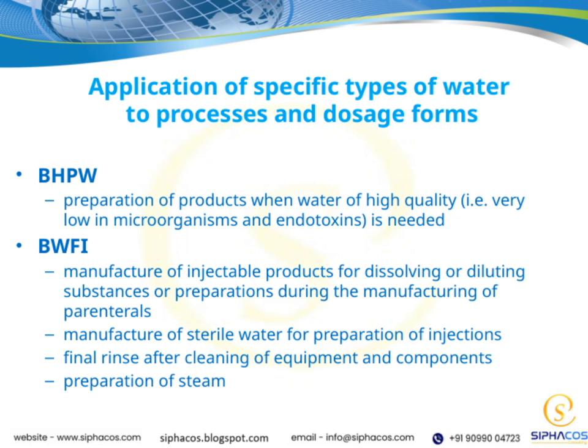Next, we have BWFI, or bacteriostatic water for injection. This is used mainly in the manufacture of injectable products, especially when dissolving or diluting substances during the production of parenterals. Because these injections go directly into the bloodstream, the water must be sterile and free of harmful contaminants. BWFI is also utilized for the manufacture of sterile water intended for injection preparations, ensuring safety and sterility.